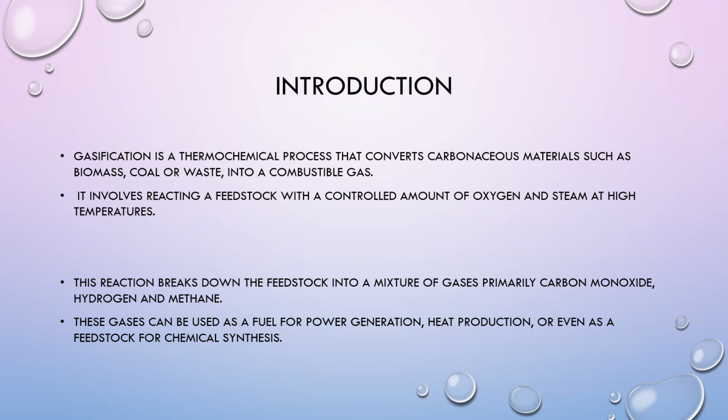Gasification is a thermochemical process that converts carbonaceous materials such as biomass, coal, or waste into a combustible gas. It involves reacting a feedstock with a controlled amount of oxygen and steam at high temperatures. So when we say a thermochemical process, we basically mean using heat to promote chemical transformations of biomass to produce energy. So in gasification, biomass is what becomes our feedstock. It's fed into the reactor, broken down to form gases, and those gases are used for heat production and power generation.